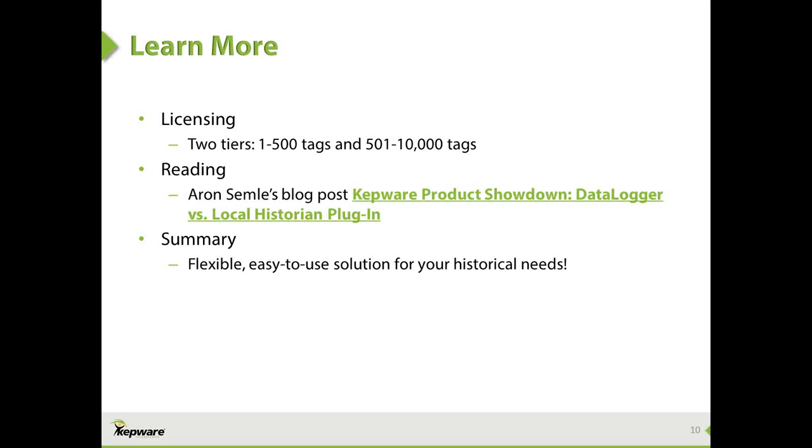And then another question from William: do you have a replay option which would feed the historical data into an OPC client via DA? At this time, we do not have such a replay option. We do have a replay option if you're storing data with a database, to maybe an Excel document or to a SQL database or an ODBC compliant database. We have something called our advanced simulator driver that does allow playback, but currently we don't have any replay options for those TSD files. So good question there. Okay, great.